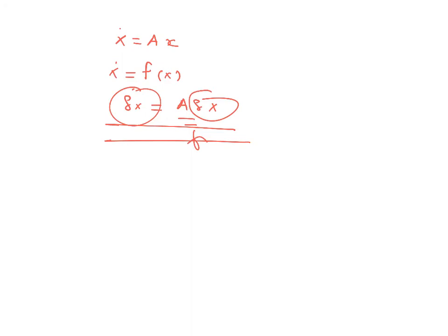So we are saying that this can still give you a picture if you linearize the system near the equilibrium point. So delta x is x minus x equilibrium, right? So we are dealing with the deviation now, and the eigenvalues of this A matrix tell you what will happen to the system when I perturb it. And if you have a small enough perturbation, then this kind of behavior will be there. Okay, so that's the thing we have here.